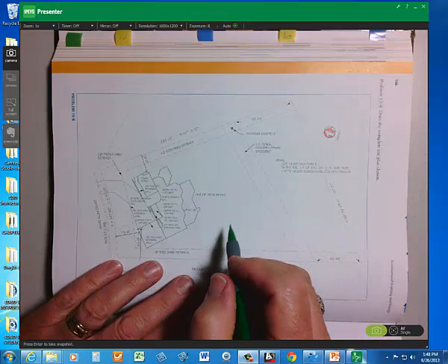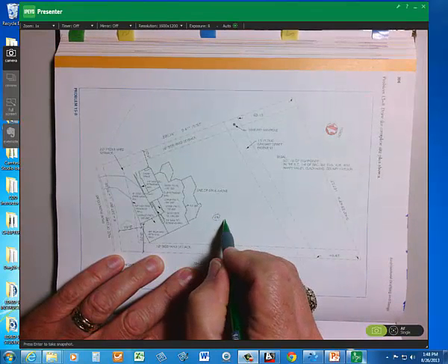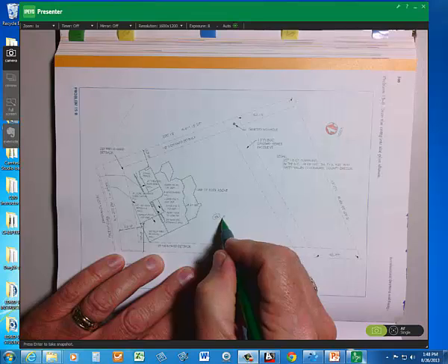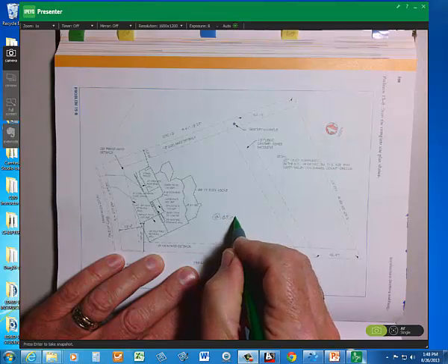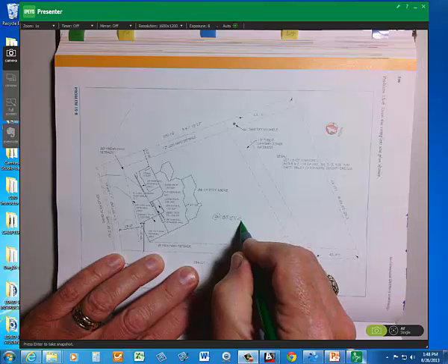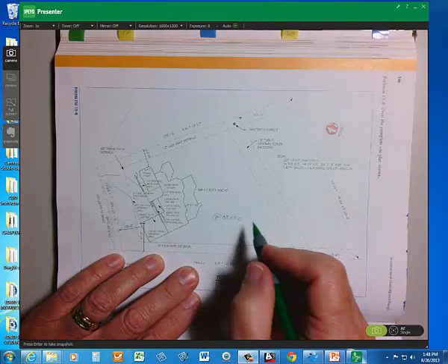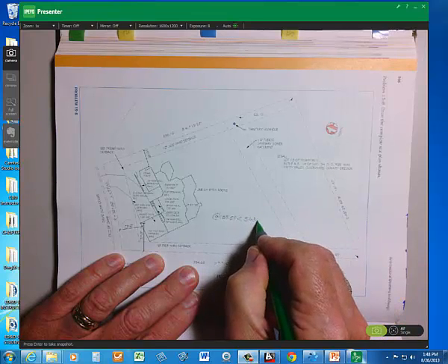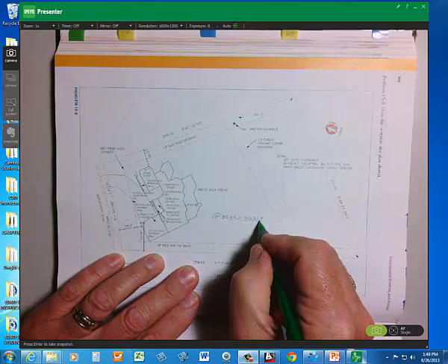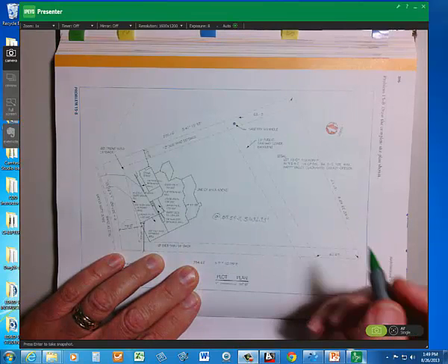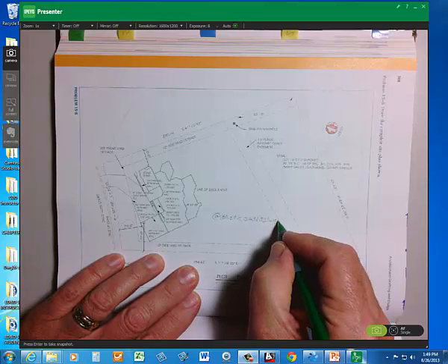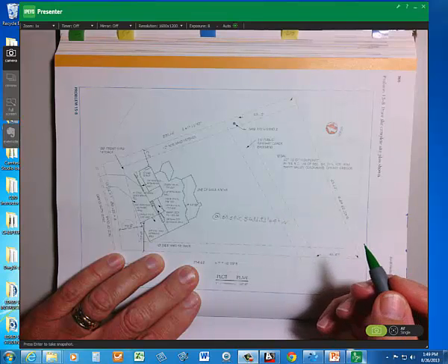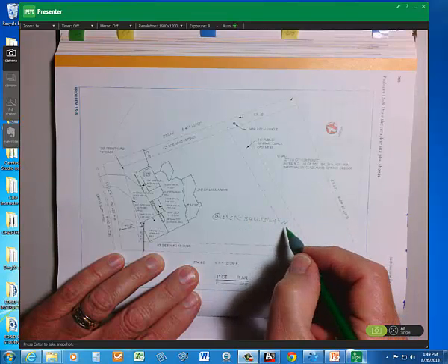So your entry will be @ the distance, which is 187.57, and then your angle sign, your less than symbol, then S, a capital S, 43 degrees, 33 apostrophe for minutes, 49 seconds, quote mark for seconds, and then a capital W, indicating that it's moving into the south quadrant.